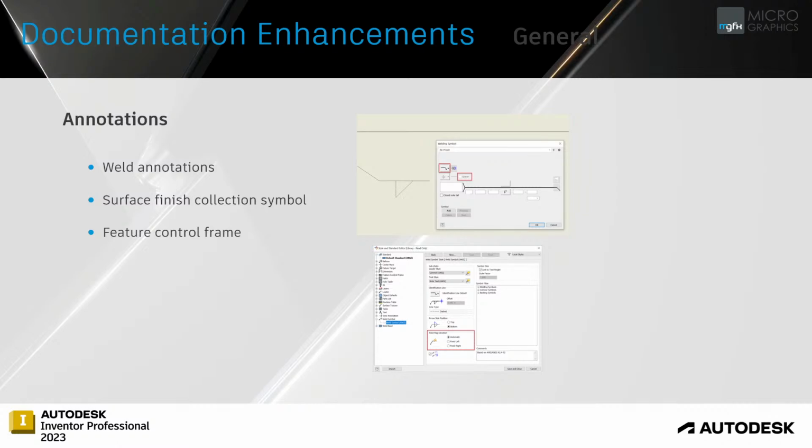If you go to your styles manager, you'll find that the field flag direction can be automatic or always fixed to the left or always fixed to the right, if you want to have some sort of convention standard. Edge weld symbols now use the latest ISO standard. The symbol is added to the style editor and enabled by default for the following standards: ISO, DIN, ANSI, BSI, GB, JIS, GOST, although that's only in Vault. So that's basically the additional features for weld control.